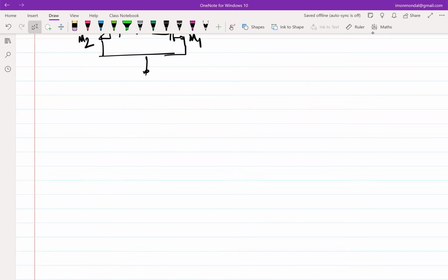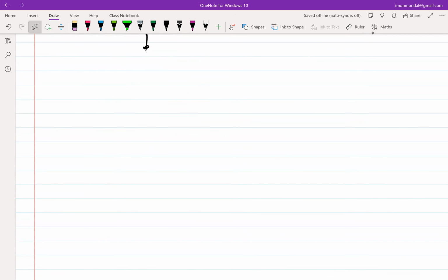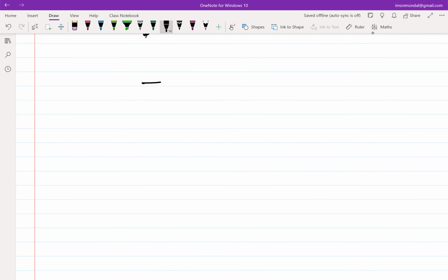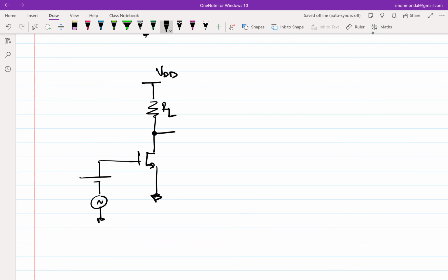So till now we essentially have been dealing with the common source amplifier, and we have wrapped it around with multiple things. We have tried to bias with multiple configurations, but every time we ended up with this gain term of GM times RL, right? So the differential amplifier was also essentially that. So let me just simply sketch a common source amplifier then. And let's assume these biases and all those things have been set up using negative feedback. So that's fine. But our gain in this case is minus GM times RL.